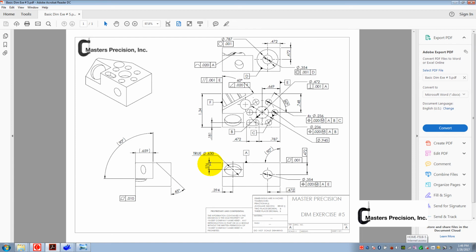All right, so now what I need to do is measure this inside here. So I got to measure a plane. To get the center point, the way I would do it would be to measure a cylinder inside there, but it's not very deep, so it's going to be tricky. But if you measured a cylinder, the axis of the cylinder would intersect with that plane, and then I could do a distance between that point where they intersected and the top plane for this 276. This one's simple. It's just the center of the circle to the edge.